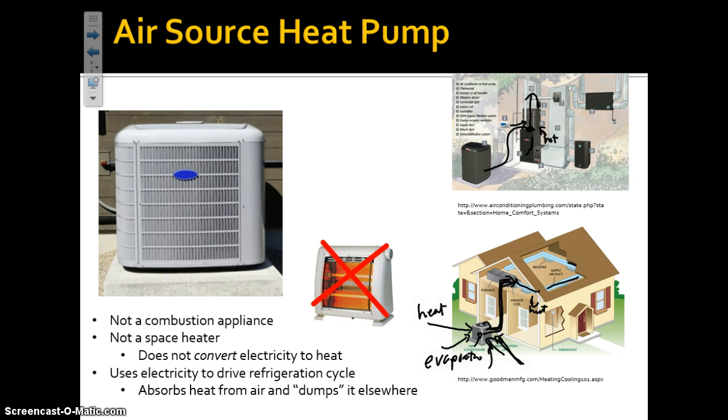Remember, it's grabbed all that heat through evaporation, and in this case, it's dumping the heat outside of the building. Okay, so then there's a fan in here that's going to blow and facilitate that heat release, and then it cools down, comes back in here, pulls more heat in, blows more cold air out, and of course you have the circulation here, comes back out, releases the heat, and so forth.